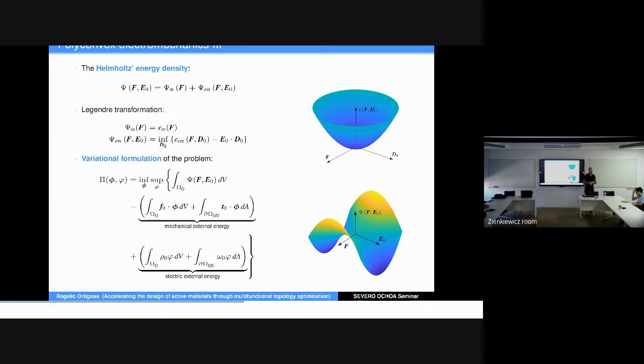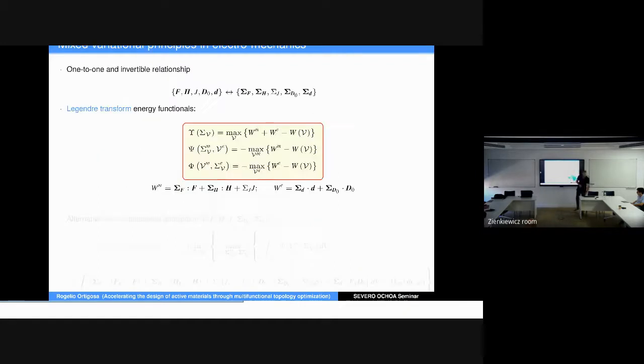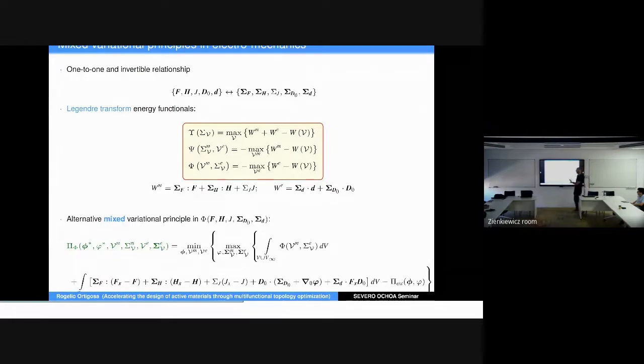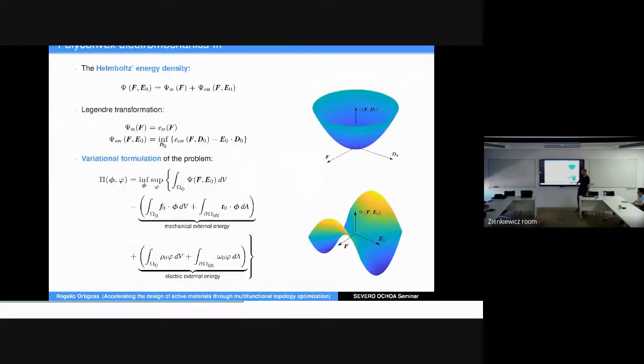And if you think in terms of the numerics, you are going to have convergence as you refine, because otherwise you are going to have extremely localized deformations in regions with 0 thickness, and you wouldn't converge. So those are the benefits of polyconvexity in terms of mathematics, physics, and numerics. But there are extra benefits from the finite element point of view. It opens up the possibility to come up with new alternative variational principles to the classical two-field that I presented here.